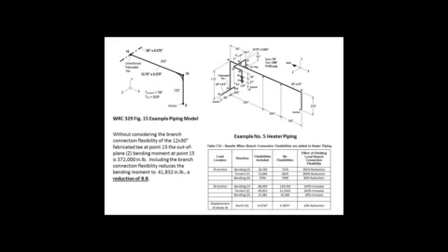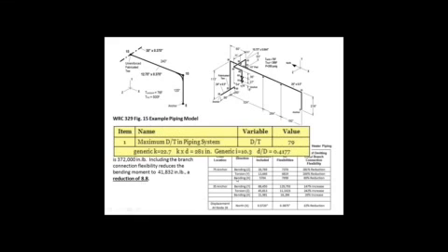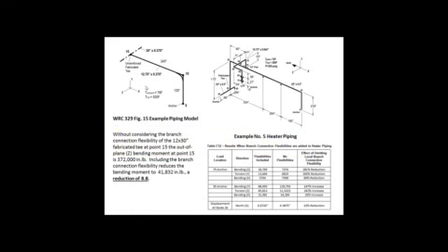Let's go to another system, or these are two systems that we've looked at before, and the left one is WRC 329. So I'll go through them just quickly. This is figure 15. It shows here what Ev showed here, that this 12 by 30 inch branch connection caused a reduction in the load of over 800%. If we go to our evaluation of this, we see that the D over T ratio is 79. The K times D is 281 inches. That's a significant amount of the length of the pipe. So the fact that the flexibility is at the end of the branch where the bending moment is the highest, the fact that the effective length is very high, says that, yeah, we would expect flexibilities to have a big impact on this system, and clearly it does.